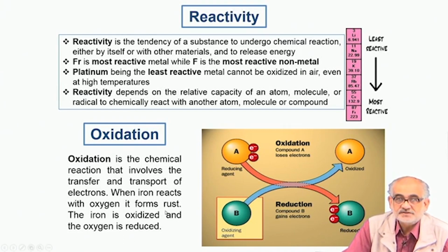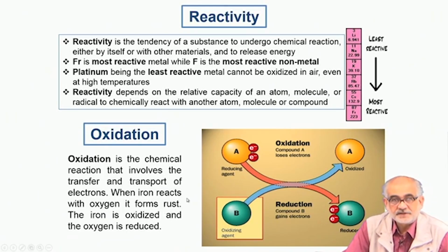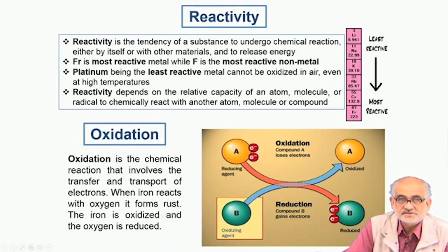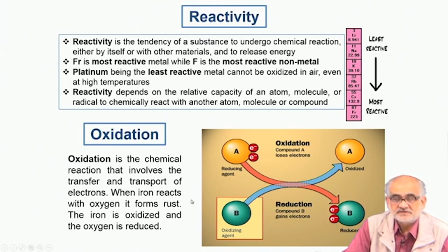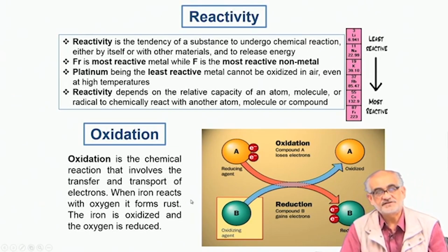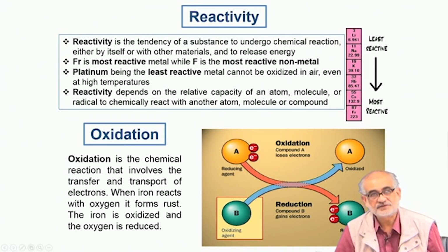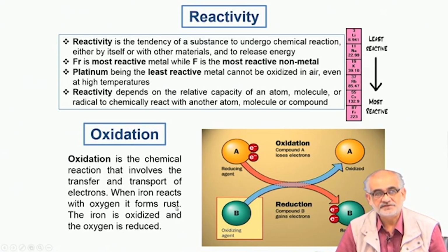It grows because it reacts with the atmosphere and forms certain hydroxides, and these hydroxides are fairly porous and structurally very different from the underlying substrate, because of which the rust spalls off the surface and exposes a fresh one, and that's how this process of degradation, or the rusting, continues.